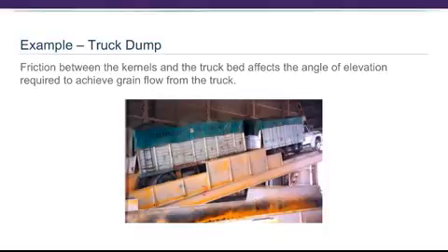So it's essentially similar to the problem I talked about before where we had a flat sheet of metal and we elevated one edge. In this case, we're just applying that same principle or concept to the dumping of a truck. Think of gravity unloading wagons and types of equipment of that sort, and this angle of friction, coefficient of friction, is going to be important for those kinds of situations.